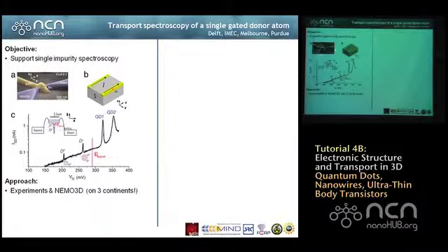This is actually a FinFET device built at IMEC. They cooled the device down, and they measured the current flow as a function of gate voltage. At low gate voltages, before the device really turned on, they see these really sharp spikes in the IV characteristic. And they hypothesize that that is really tunneling through single impurities. Okay? So that is what I'm going to describe in the next few slides.